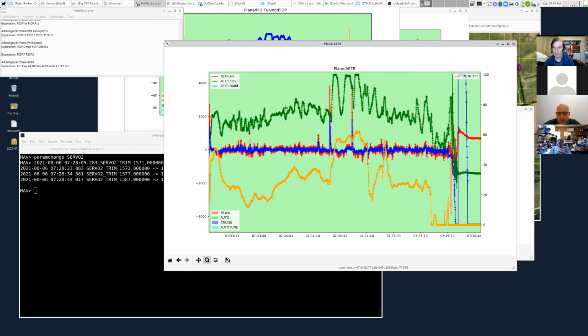So he'd have to look at it himself and check. The Volantex EX has little markers for the center of gravity under the wing. So when you're not out in the wind, you can come indoors and balance it on your fingertips and see if it's balancing at the right point. Although you've got to be careful, some manufacturers get those center of gravity points wrong.